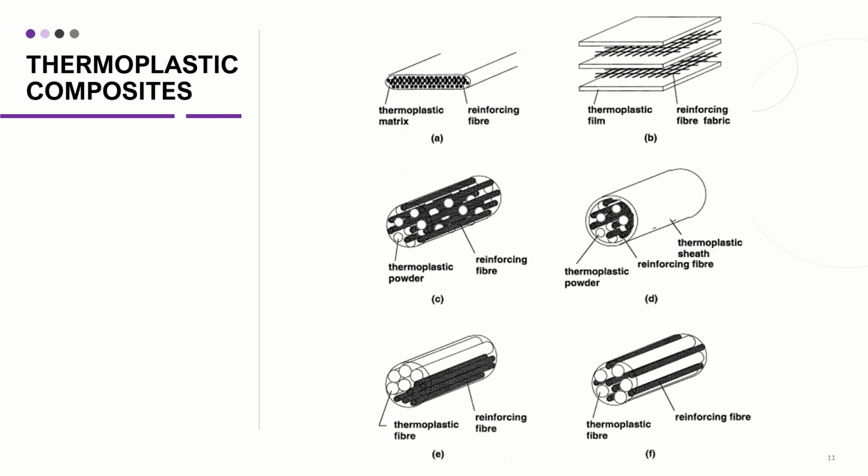As part of the turbine blade manufacturing workflow, thermoplastics offer processing cost improvements while maintaining the required mechanical properties. The infusion and curing time is reduced by 6 times, and the material is 20% less expensive than a traditional epoxy.